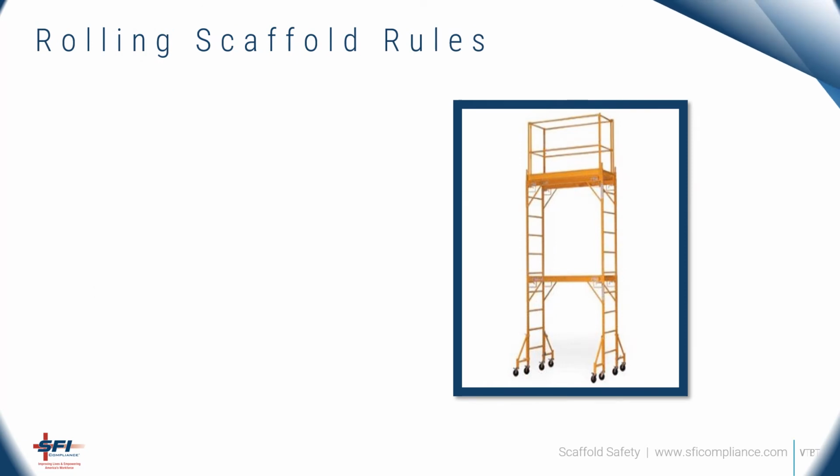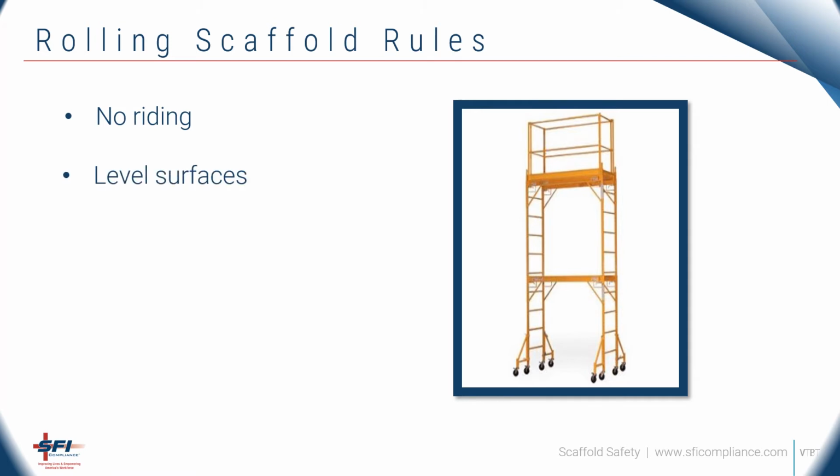When using a rolling scaffold, it is recommended that you follow these rules. No one is allowed to ride rolling scaffolds. Rolling scaffolds shall be used on level surfaces. The height of the rolling scaffold must not exceed 4 times the minimum base dimension. Use outriggers if additional height is needed.